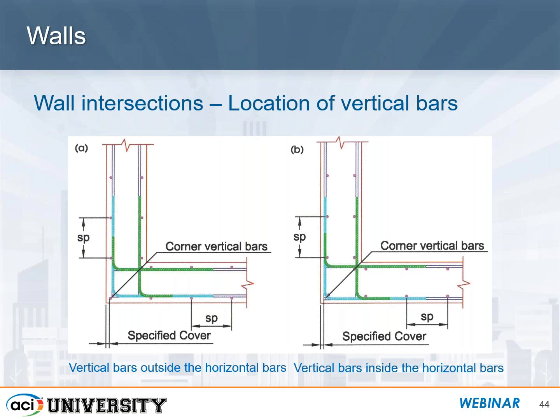Okay, thanks. It wasn't clear. All right, there's two questions that are very similar, and I'll phrase it one way. There may not be enough development embedment for either the vertical bar with a hook or even a smaller side dowel with a hook. Cases where this may occur are on the exterior of a building and may require a column capital. Any suggestions? The other one says terminate at the longitudinal column bar in the roof slab. So they're concerned with proper development length of the end bar hook.